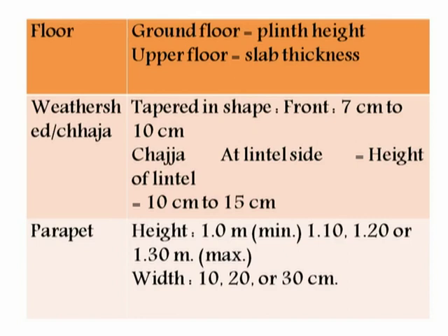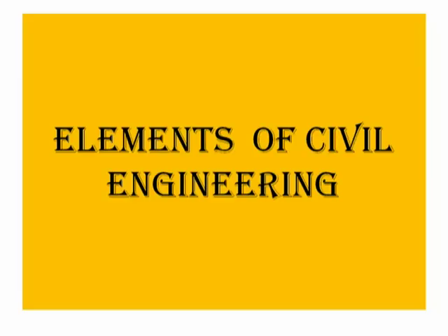At the end we will see the parapet. The height of the parapet is around 1.1 or 1.2 meter or it may be up to 1.3 meter. The width of the parapet will be 10, 20 or 30 centimeter.